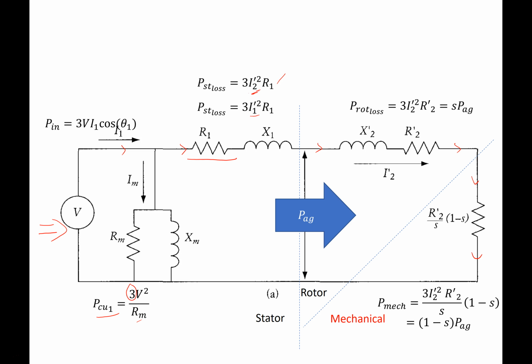But remember, in reality, this is a simplification. It is a modification of the equivalent circuit. The original equivalent circuit we developed had the core branch on this side. And if the core branch was on this side, then the current here would be I1. So that is why you get sometimes the I1 being used, sometimes I2 being used.